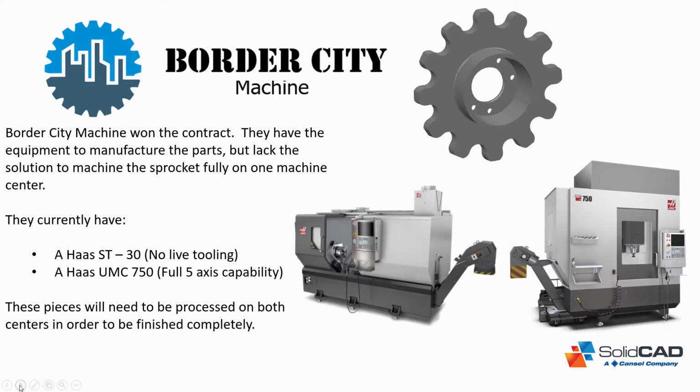This Sprocket requires a large amount of turning and milling, so they will need to incorporate both pieces of equipment into this production run. Now, PowerMill does have some turning, but it really doesn't support these type of multitasking centers. But since they're on subscription, they can use Fusion 360 with an available post-processor found online to turn these parts and then move them over to their Haas UMC 750 to finish off the milling process.